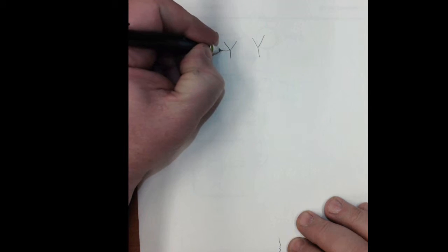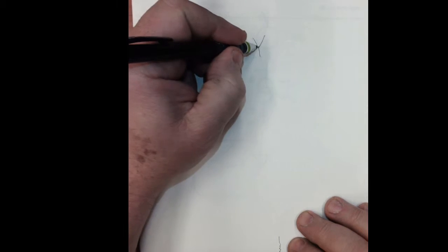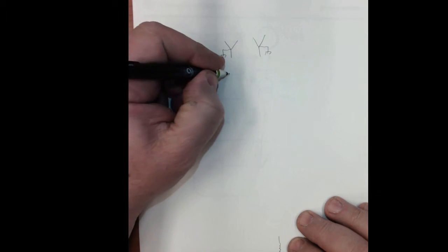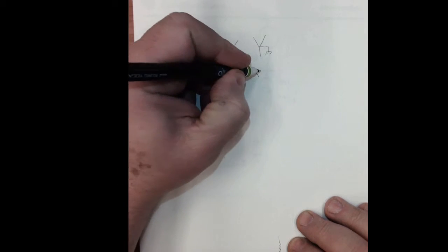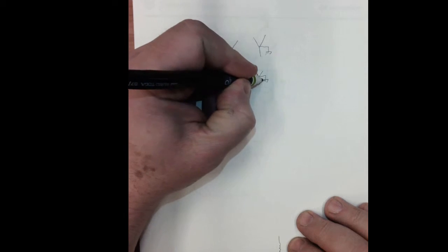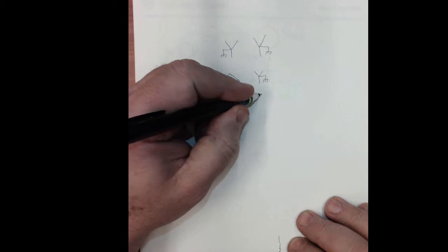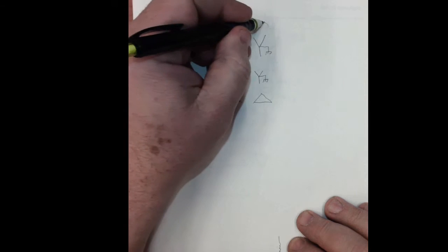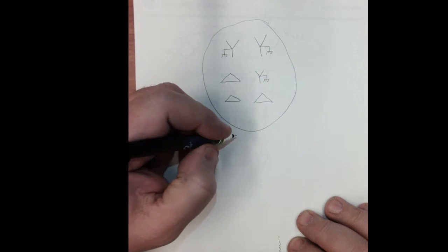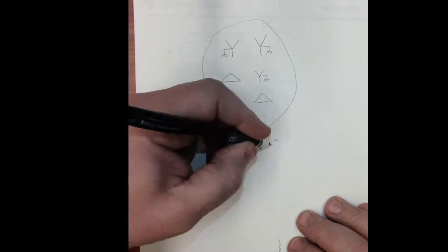I can ground either side, one side or the other, or I could ground both. Probably the most common form of transformer we see in electrical systems is where I have a delta connection on the primary side and a Y connection on the secondary side. And I can also see transformers where I have a delta and a delta connection. Now, the significance of these types of connections comes into play when we look at our zero sequence network.